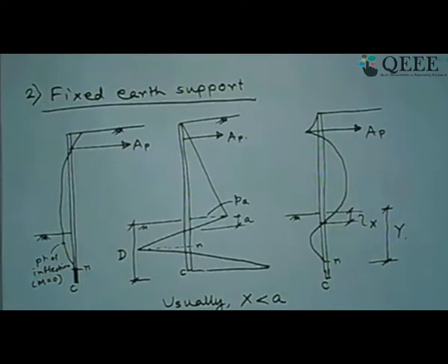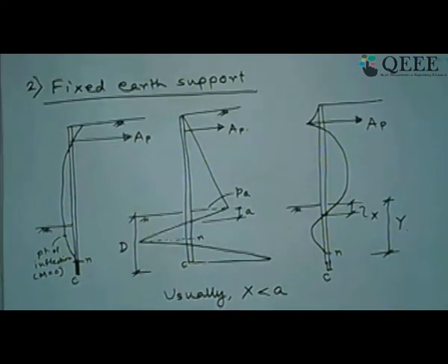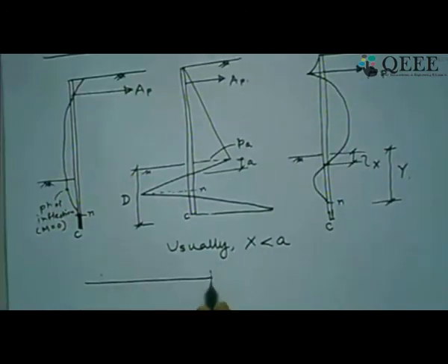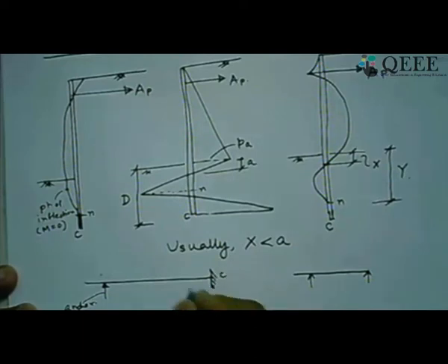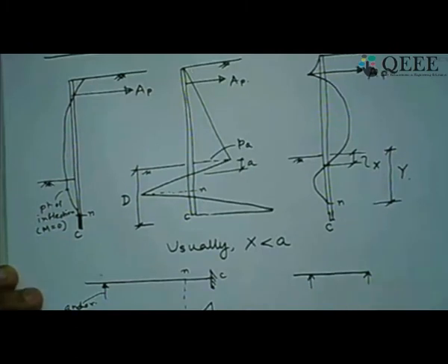So what we can consider here, we take this bending moment diagram as we do for the beam. So we will take a fixed support with a prop, which is nothing but the anchor location. So if you try to correlate, this is similar to what we know about the bending moment diagram of this kind of beam. Now one can idealize or assume it something like this. Instead of this fixed end, that is, instead of going up to the point C, you stop somewhere here, which is your point N, and consider the support here, such that your moment diagram is something like this, which is what we are trying to impose here.